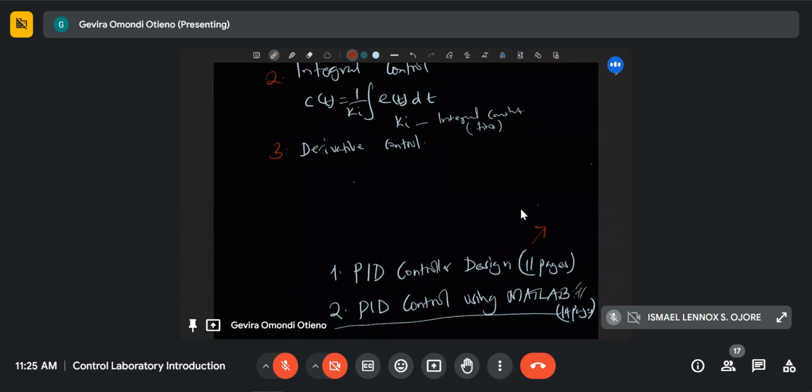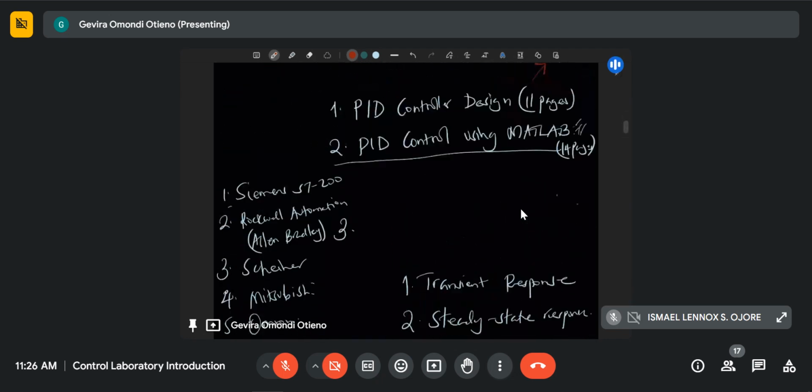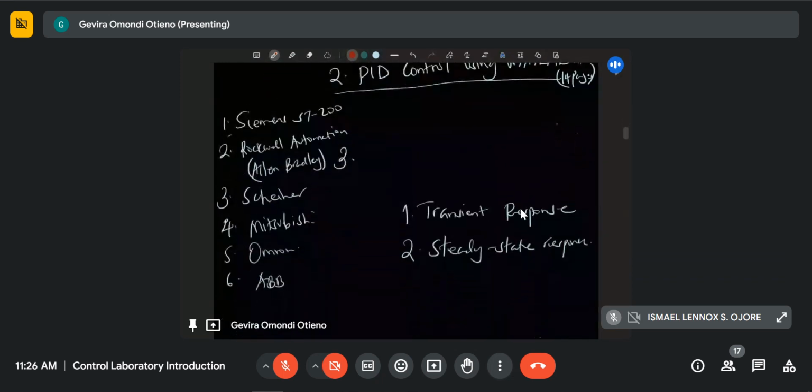It tells you, this is the transfer function of our system. Please enter this code in MATLAB. Then all you have to do is observe and plot, check the plot, okay? And once you do that, you will be seeing the different effects of increasing and decreasing the values of Ki, Kp, and Kd.